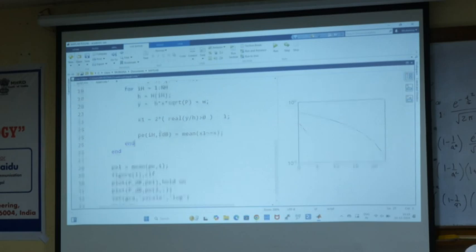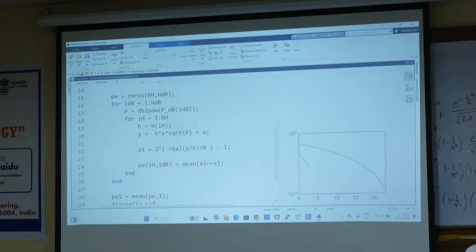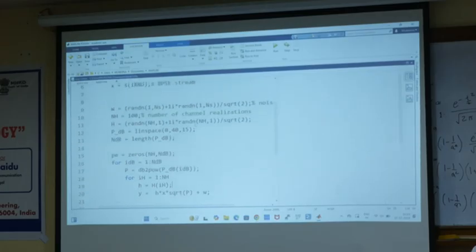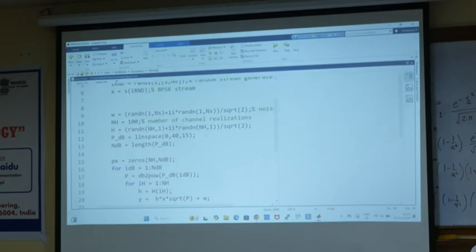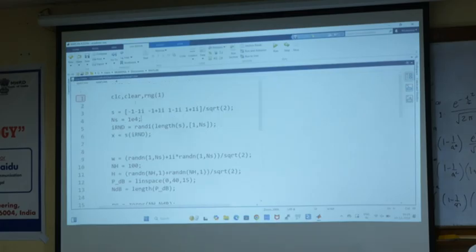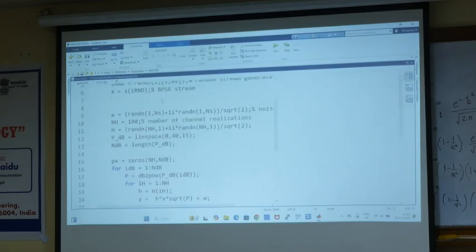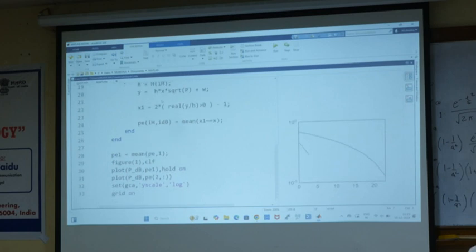How do we use non-linear things? We split the non-linear things into small linear parts, and in that small part it becomes linear. Similarly here, frequency selective means only over a little bit of bandwidth it is constant. Over that little part only we can use. So we have to divide the frequency selective channel into flat fading channels. You understand? You are understanding what I am telling now? H is constant.